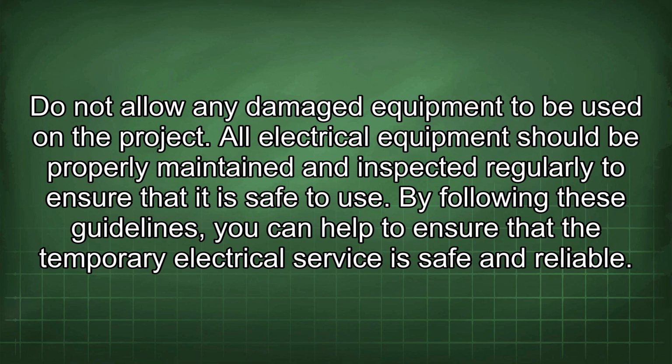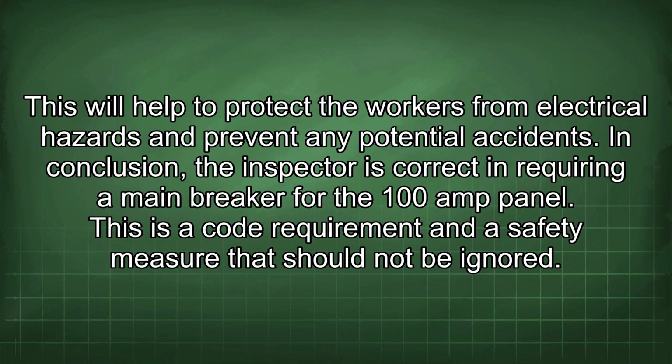All electrical equipment should be properly maintained and inspected regularly to ensure that it is safe to use. By following these guidelines, you can help to ensure that the temporary electrical service is safe and reliable. This will help to protect the workers from electrical hazards and prevent any potential accidents. In conclusion, the inspector is correct in requiring a main breaker for the 100 amp panel. This is a code requirement and a safety measure that should not be ignored.